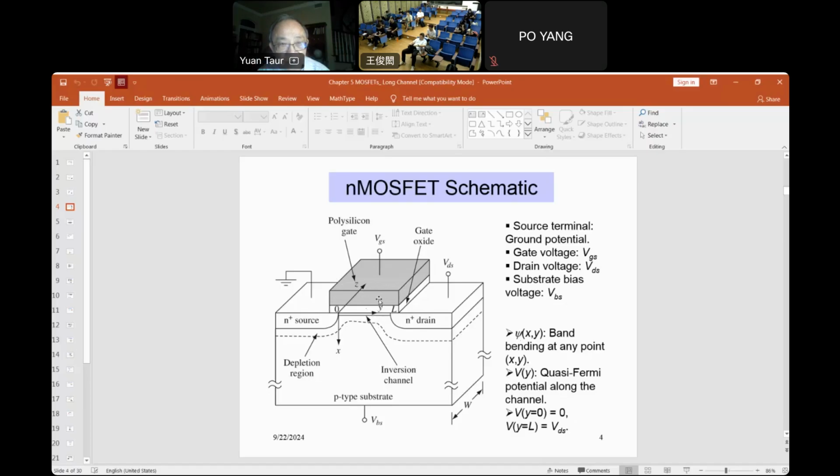And it's a transistor because it's a 3-terminal, actually 4-terminal, device. But the current flows between source and drain. That's terminal 1, terminal 2. But that current is controlled by the third electrode, that's the gate. So source to drain current controlled by the gate, and that's the basic definition of a transistor.